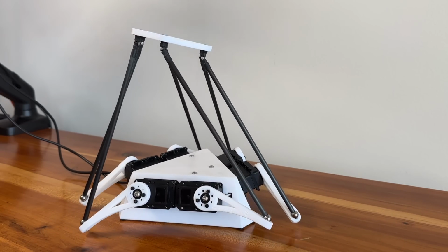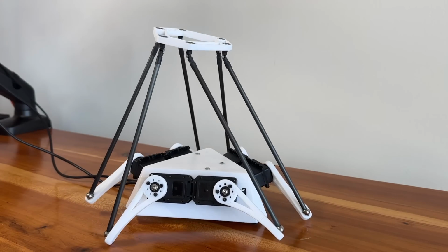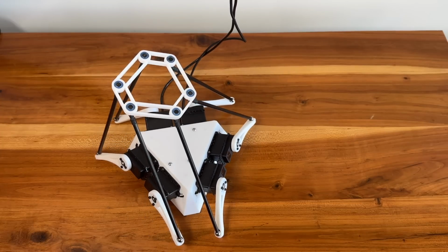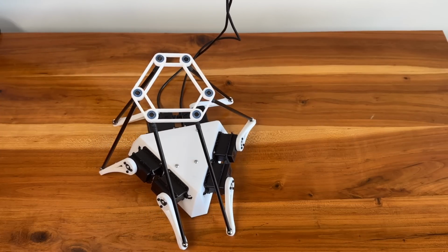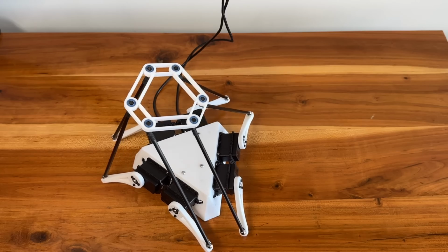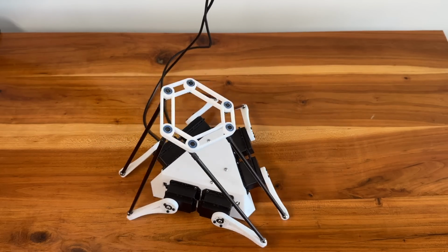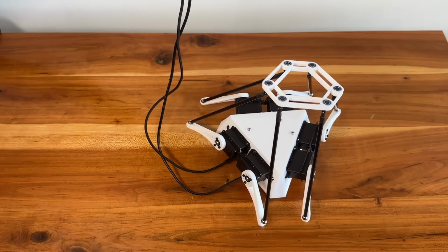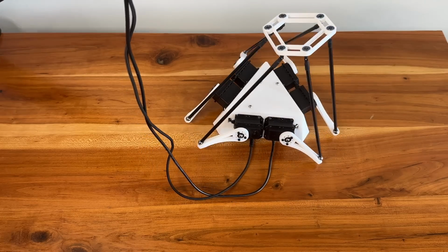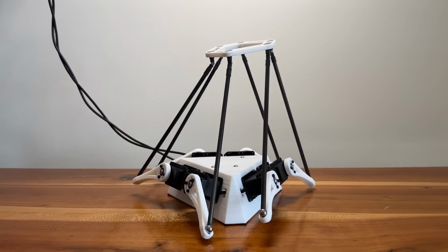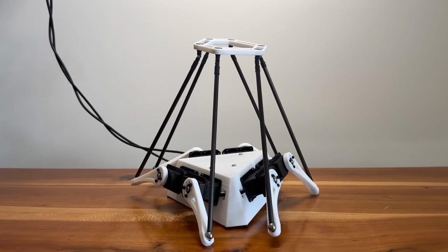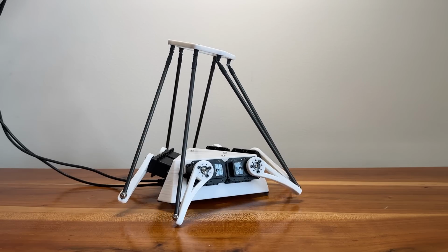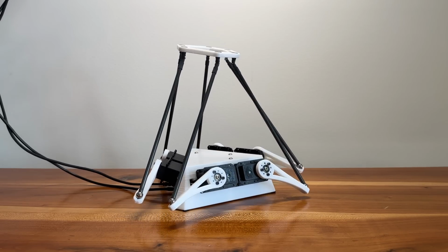Here's one that uses 2 of its arms to move. The fitness function thought it was traveling really far, but that's only because the simulation only lasted for 10 seconds. If it had been longer, it would have seen that the robot was just pivoting around in circles. To get it moving in a straight line, I modified it to mirror the movement across the center line every other cycle. This causes the top plate to snap to the mirrored position between cycles, and probably breaks the speed limit I had varied the period to meet. But it doesn't seem to hurt anything, so I'll go with it.